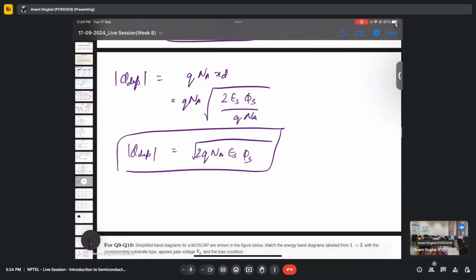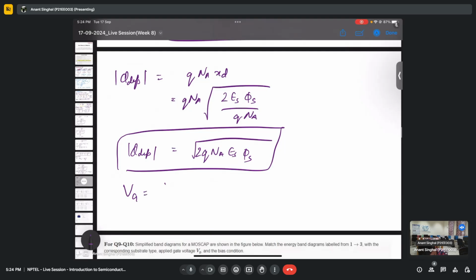So now what we have reached is, I hope you remember that we were doing this, that the gate voltage is applied till we depleted the carrier. So the gate voltage right now is VFB plus the square root of 2q epsilon s psi s na by Cox.